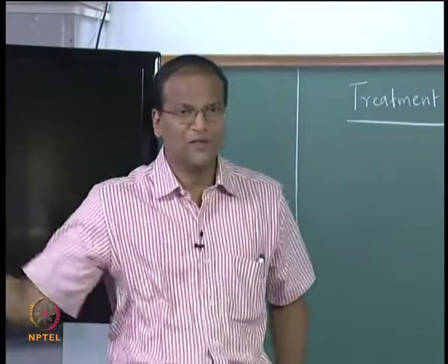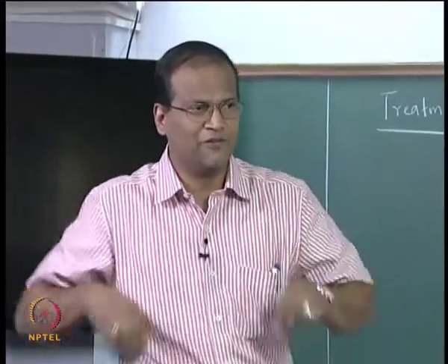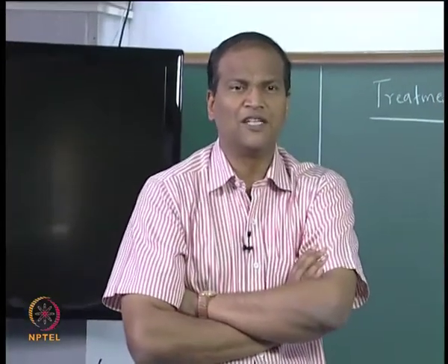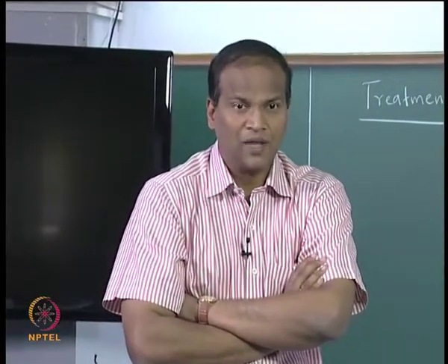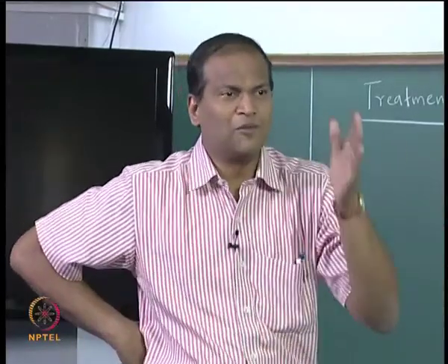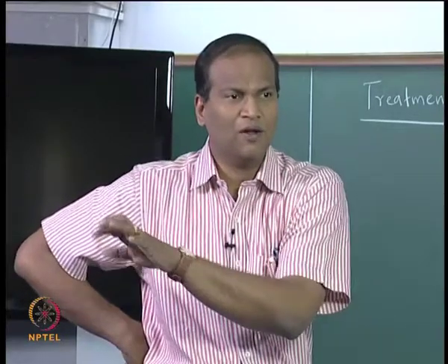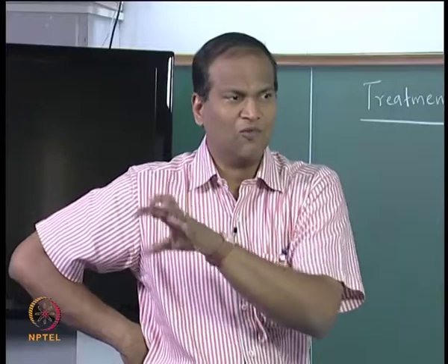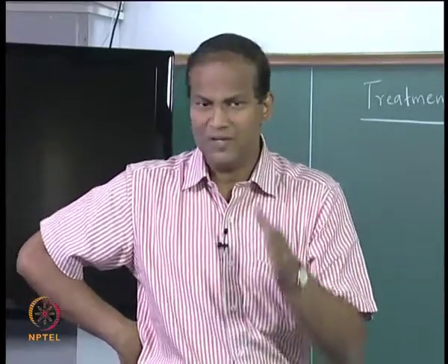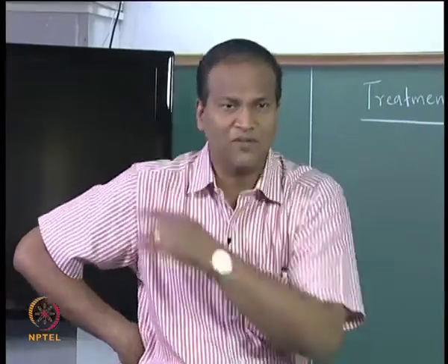So Deepak is coming out with some answers, he is saying that we have to use the f function chart. So if you have to use the f function chart, that means you have to use the f function charts for different ranges of the interval. Are you getting the point? If lambda is equal to 0 to infinity, if there is a value of epsilon 1 for 0 to 3 micrometer, then you will use some f function chart and find out what is the total amount of radiation in terms of sigma T to the power of 4, how much of sigma T to the power of 4, then 4 micrometer to 7 micrometer, 7 micrometer to 9 micrometer, whatever up to infinity.